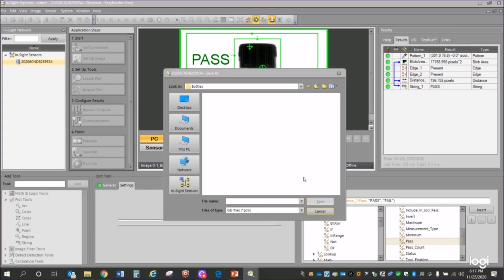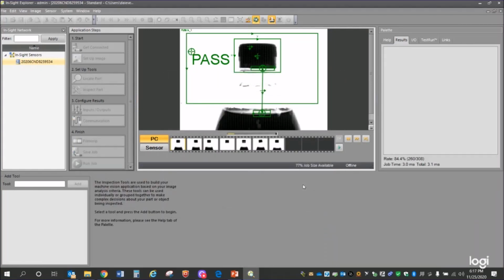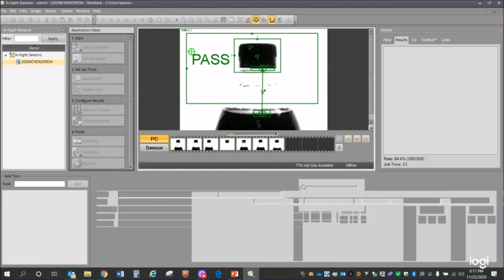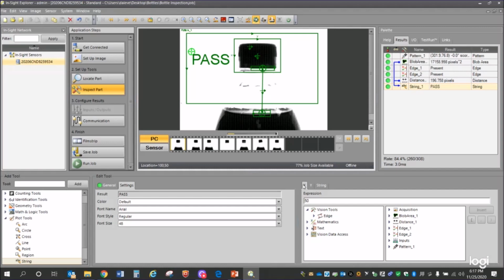And assuming that I was working with a genuine camera, the steps are exactly the same. Jeremy Berg, what is the most important variable when dealing with machine vision systems? Lighting, lighting, lighting. It's all about lighting. If you can't control the light, you will not be able to process the images. If the light changes, your inspection tools will stop working.